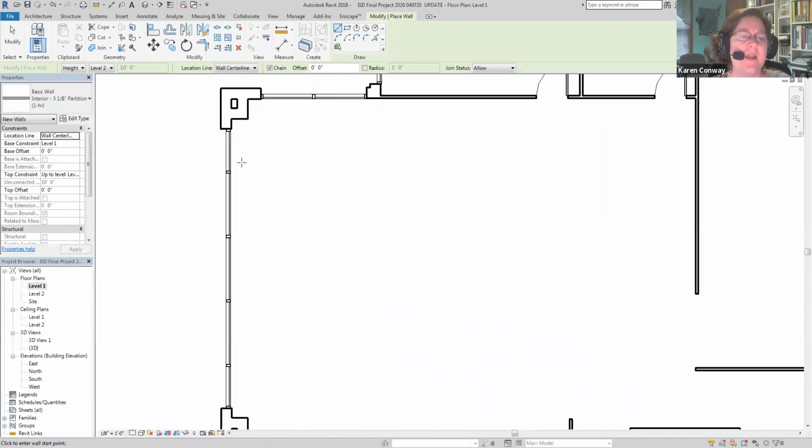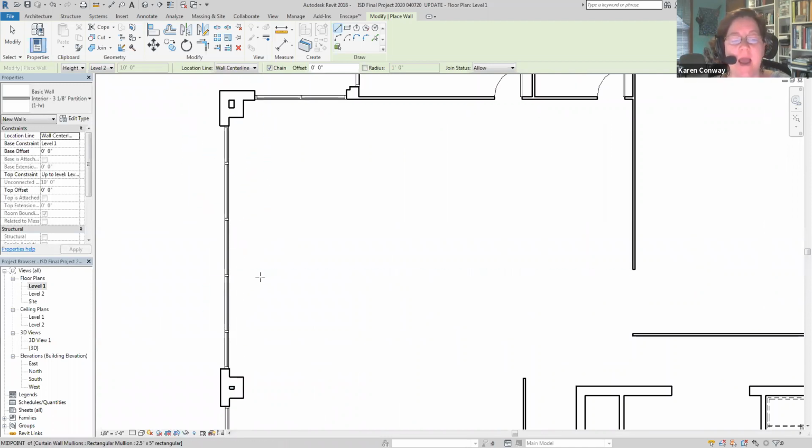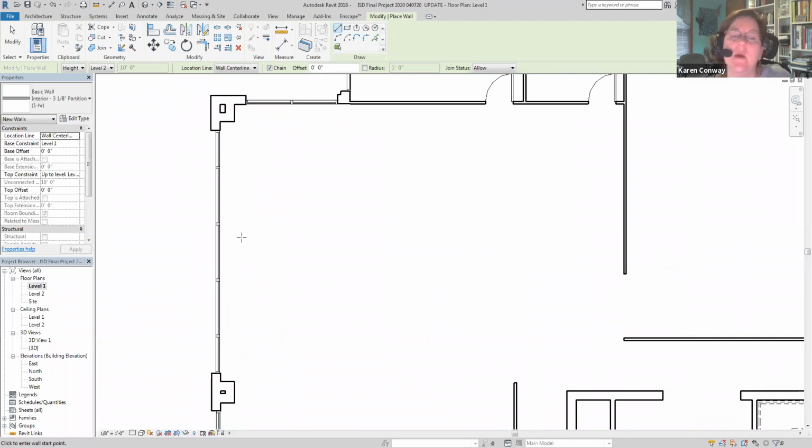So what Anthony and I were talking about is, when you look at this building in 3D, this is the glass, this is the mullion, these are the dividers. Most of these panels at max are going to be 6 feet wide. That's kind of the default that Revit puts them in. I edited it a bit so that the 6 feet is all centered, and then you have maybe like 4 on each side. So pay attention to that.